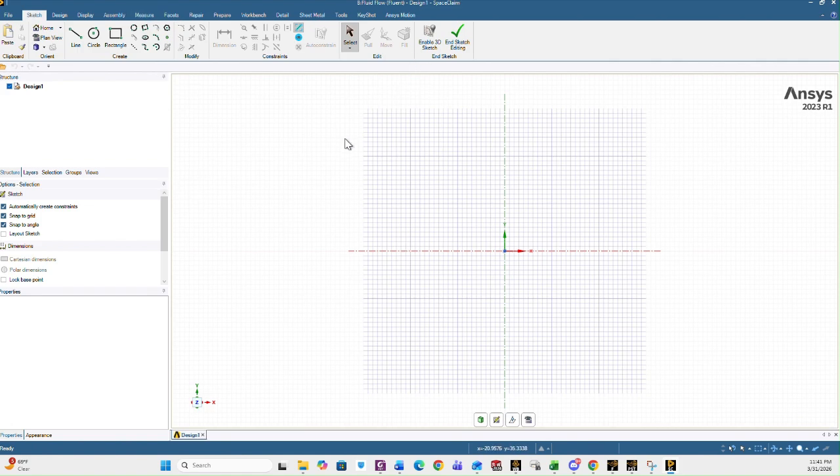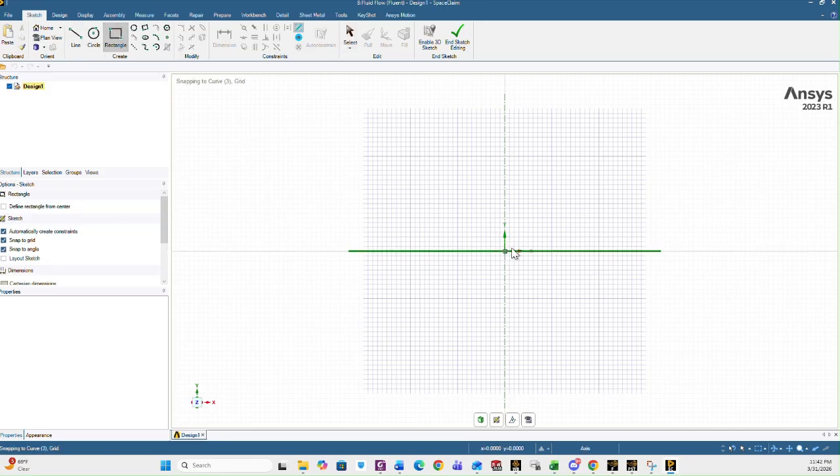Okay. So since we're doing 2D Poiseuille and Couette flow, and it tells us that the conditions are going to be viscous, steady, laminar, and compressible. Free stream is at 5 meters per second. The top plate is moving at 3 meters per second, and the bottom is moving at -2. The length and height, they want it to be 150 times the height. So let's go ahead and just make a rectangle like this, and then 150 times. So I'm going to make this 150 millimeters.